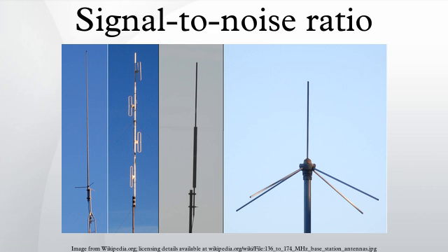Quantization noise is modeled as an analog error signal summed with a signal before quantization. This theoretical maximum SNR assumes a perfect input signal. If the input signal is already noisy, the signal's noise may be larger than the quantization noise. Real analog-to-digital converters also have other sources of noise that further decrease the SNR compared to the theoretical maximum from the idealized quantization noise, including the intentional addition of dither.